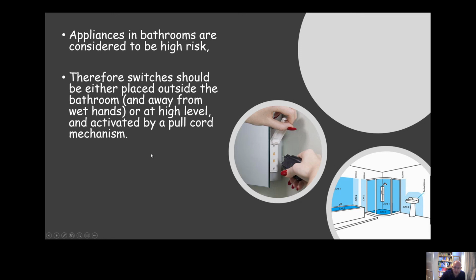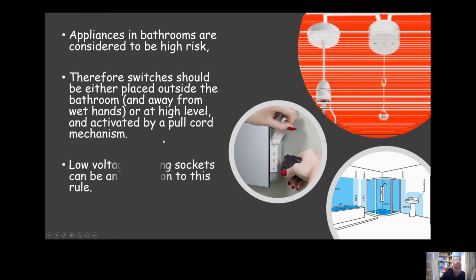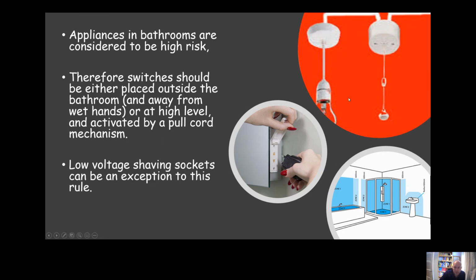But generally speaking, as a rule of thumb, we'll keep all rocker switches outside of the bathroom and use pull cord switches inside the bathroom, which means that wet hands aren't going to come into contact with the actual switch itself. You can use low voltage shaving sockets in the bathroom, but that's because they are low voltage. They're not really a significant risk.